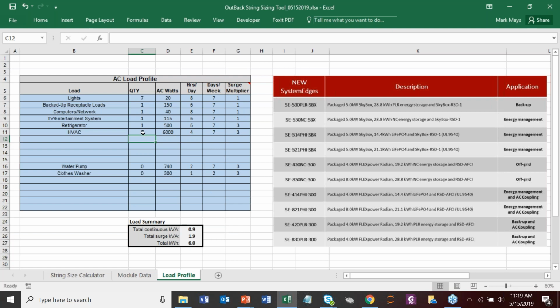However, nearly everybody I talk to wants to back up air conditioning, and one strategy that you might want to consider, since air conditioning takes up so much energy, is to maybe think about a compromise. You could talk to your customer and say, okay, how about if we go with a 1500 watt mini split and put that in a cooling room? So the family room where the TV and the entertainment system is, we'll just put a 1500 watt mini split in there, and that'll be the cooling room as kind of a compromise.